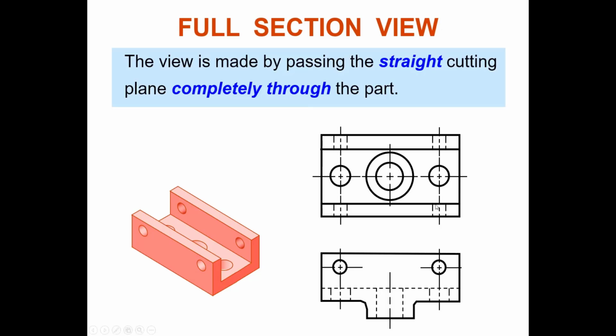So it is better if you have a lot of complicated lines like this and you put dimensions. It's kind of hard, because when you do dimensioning, try to avoid dimensioning the hidden lines. That's why, as I mentioned earlier, if not, the answer is yes, pass, done. Then if no, you have to look at your section view convention. So you have to do a section view, to make a simplified version.